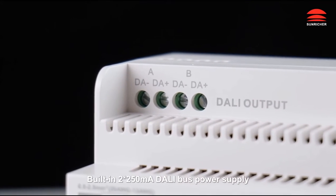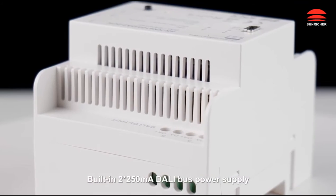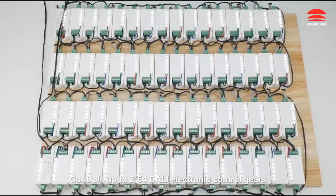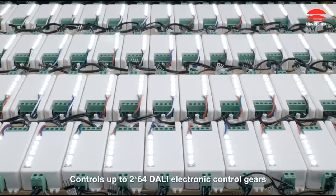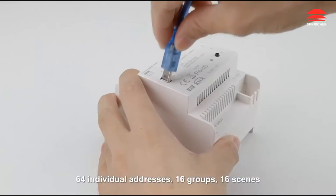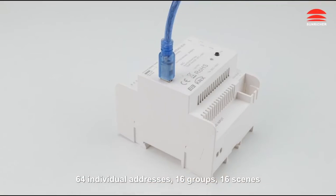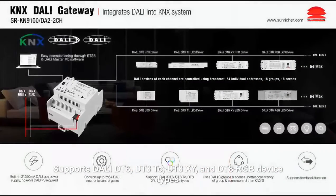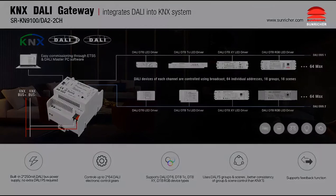Built-in 250 mA DALI bus power supply, no extra DALI power supply required. Controls up to 264 DALI electronic control gears. 64 individual addresses, 16 groups, 16 scenes. Supports DALI DT6, DT8TC, DT8XY, and DT8RGB device types.